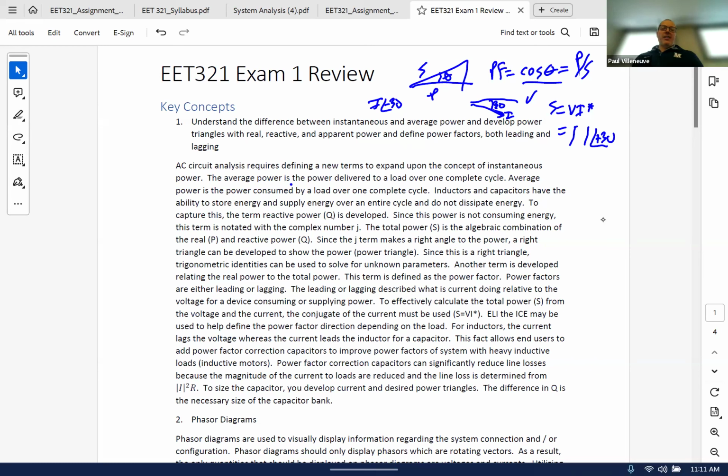One student asked this question this morning about impedance. You've got to be very careful about when you use I squared R, V squared over R, I squared X, V squared over X, I squared times Z, V squared over Z, because all those equations are based on S equals V I conjugate. So it's okay to use I squared R and I squared X. It is not okay to say S equals V squared over Z or I squared times Z, because that's only going to give you the magnitude of the impedance. It doesn't give you the real part or the imaginary part.